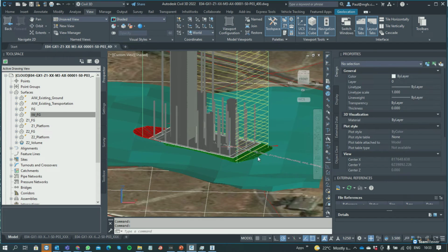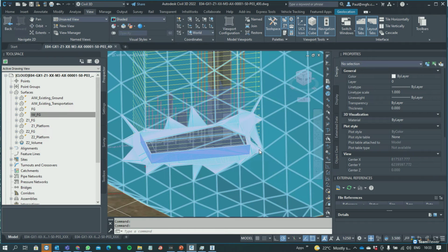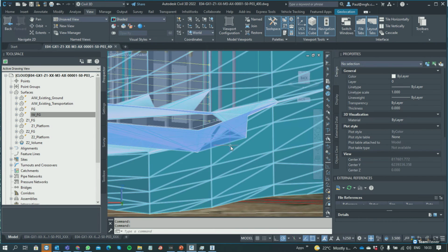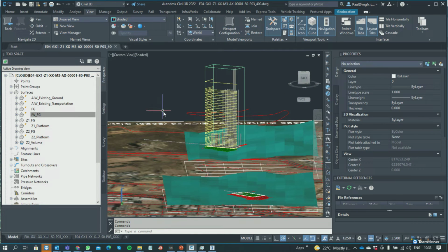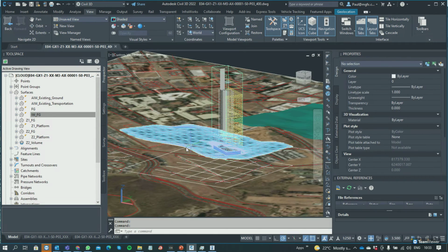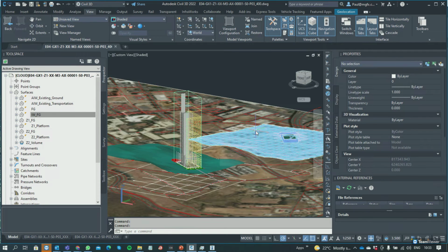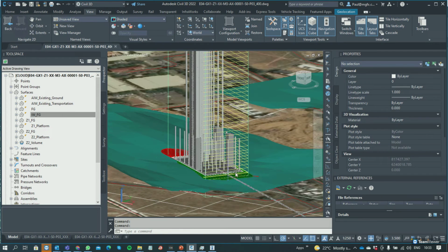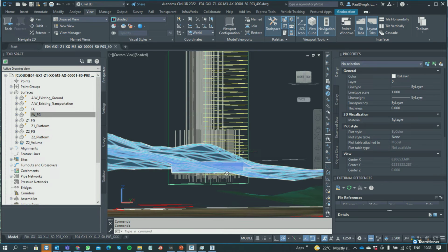These surfaces I could then use for a topography that I prepare for Revit, or for sharing into Revit. So there's an example of, as a first-pass approximation for a Revit project, I used the data that's available within Infraworks to bring into Civil 3D, from where I can do terraforming and prepare a basis for my buildings.